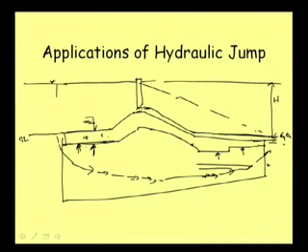But for this part of the floor, we can see that the uplift pressure from this side is this much, and from the top we do not have sufficient water, we have only this much of water. So, uplift pressure will be quite significant, and then we need to design this floor so that it can resist the uplift pressure. So, the thickness of this floor becomes quite large. As we are going down, uplift pressure is reducing and thickness is also reducing, but it is quite large in this direction.